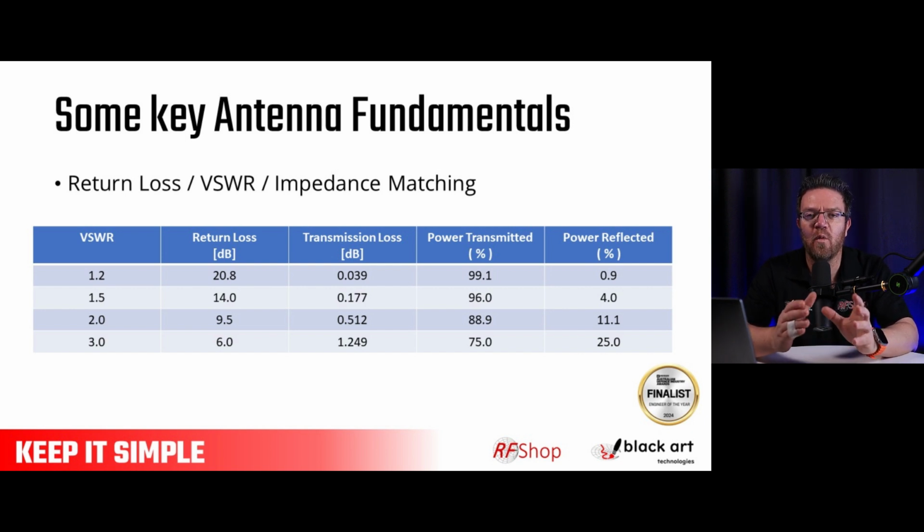So meaning, how well does your circuit then flow into the antenna? If they are the same value, that flow from one to the other, the impedance on this one and the impedance on that one is very similar, and it just flows through. It's really like water flowing. It's the same logic, it's the same principle. But if there's a big mismatch, this is my system coming in, this is small, this is much bigger, there's going to be discontinuity between the two, and that discontinuity can give you a lot of problems, which is what I show on the slide here.